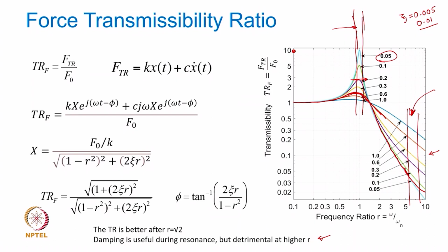But then of course, it will add to the complexity of your systems and so on. So, as long as you are ready to shell out more money in the design, you can in fact develop your own semi-active kind of system, where certain dashpots have interesting properties. You basically have probably a constant stiffness, but the damping coefficient is what I call a modified or changeable damping coefficient. So, the C value gets increased here by activating magnetorheological action or the fluid which is there in the dashpot.